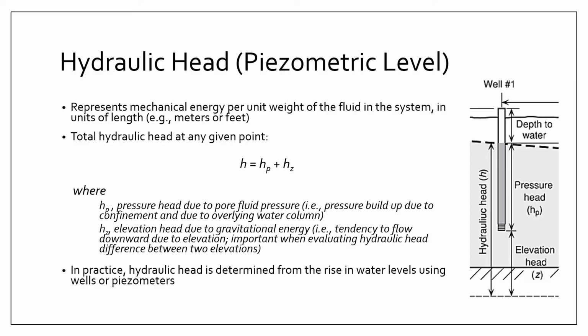Now let's talk about the inputs individually. Let's talk about hydraulic head, or the piezometric level. Note that hydraulic head is expressed in units of length, typically meters or feet. And strictly speaking, hydraulic head represents the mechanical energy per unit weight of the fluid.